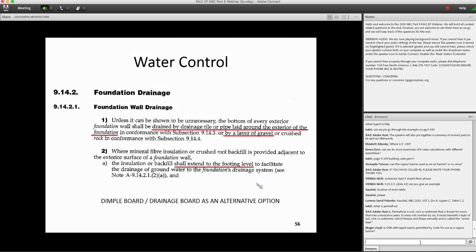It's not just about waterproofing. Waterproofing will prevent water from coming in. The better and more expensive it gets, the more resistance you have, but you also have a way of decompressing the hydrostatic pressure, and that's by draining the below grade assemblies.